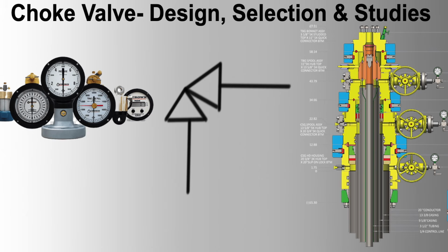3. Seal degradation. Problem: seal materials degrading under high temperature and pressure. Solution: choose high-performance seal materials like Viton or PTFE. Regularly inspect and replace seals to maintain leak-tight performance.